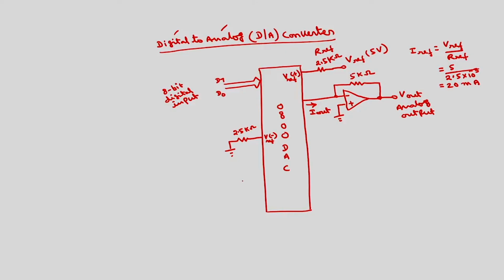Then we have some threshold control signals. This is pin number 1, 3, 16. This is 0.1 microfarads, this is 0.01 microfarads. These are basically used for removing the noise, and here this will be given to minus 12 volts. And we require a VCC and ground. So, this is the VCC pin, this is the ground pin. VCC can be plus 5 volts or plus 12 volts. This is totally a 16 pin IC. There are total 16 pins.